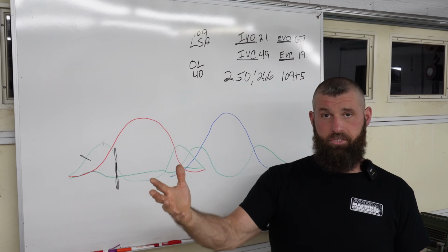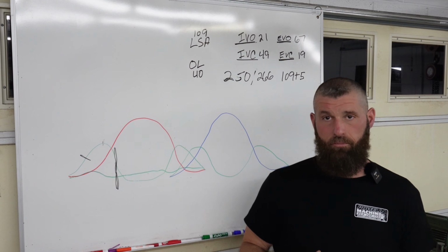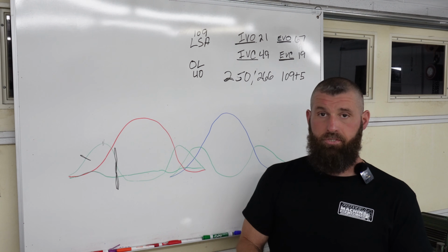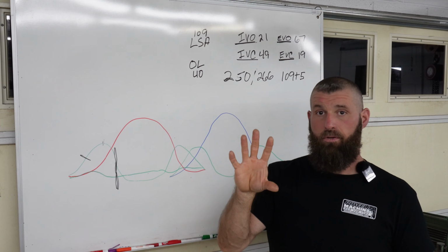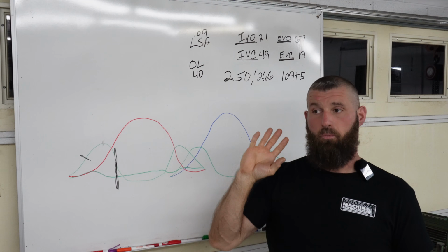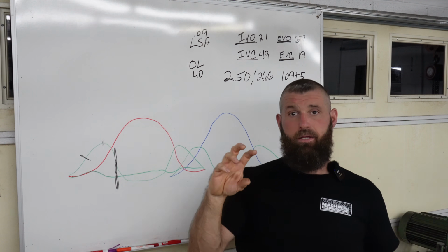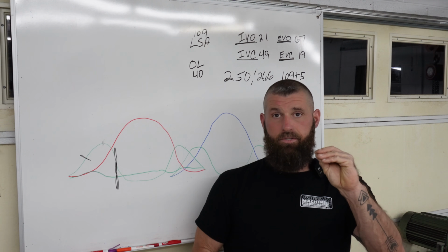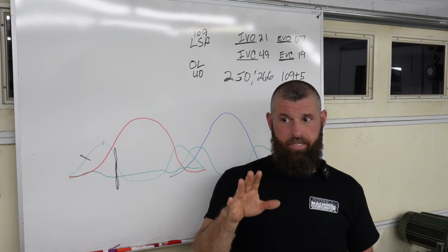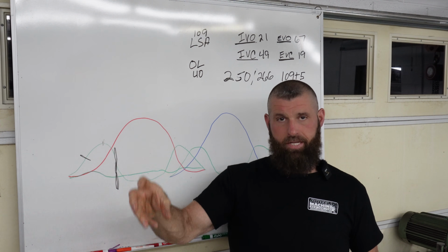he actually has a chart from observation on the Spintron that he was nice enough to share with me that has pushrod diameter, pressure, and RPM for deflection. And it's like a sliding scale. So we can determine how much bigger we need to make. So there's calculated duration, right? It needs this much duration, but it actually needs this many more degrees because of deflection.